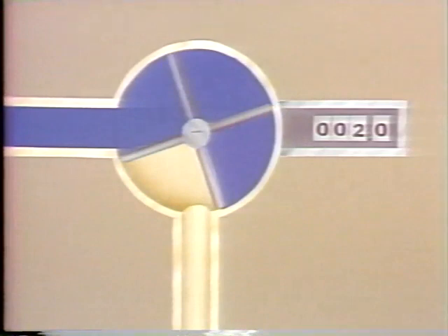The meter counts the number of times that the wheel rotates. Since each turn of the paddle wheel represents a known volume of fluid, counting the number of times that the wheel rotates over a given period of time will give you the flow rate. Positive displacement flow meters can be found in a variety of locations in a plant.